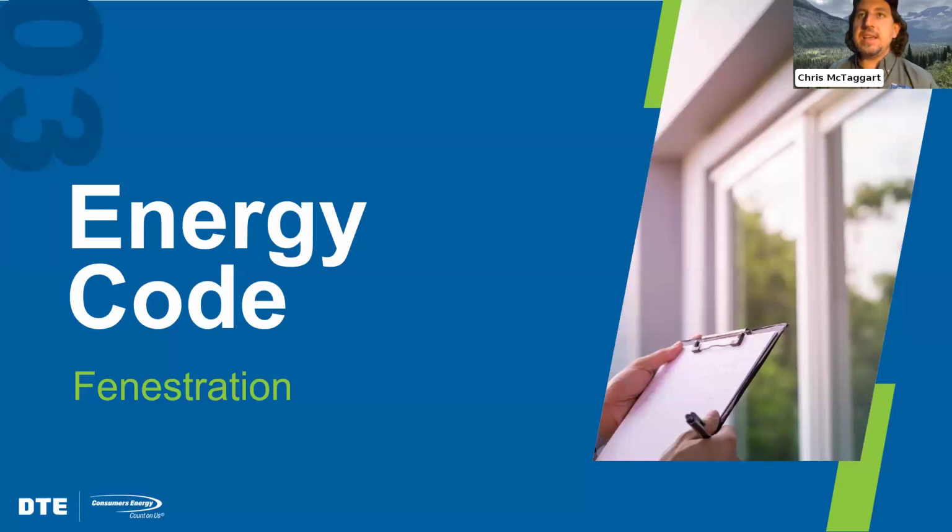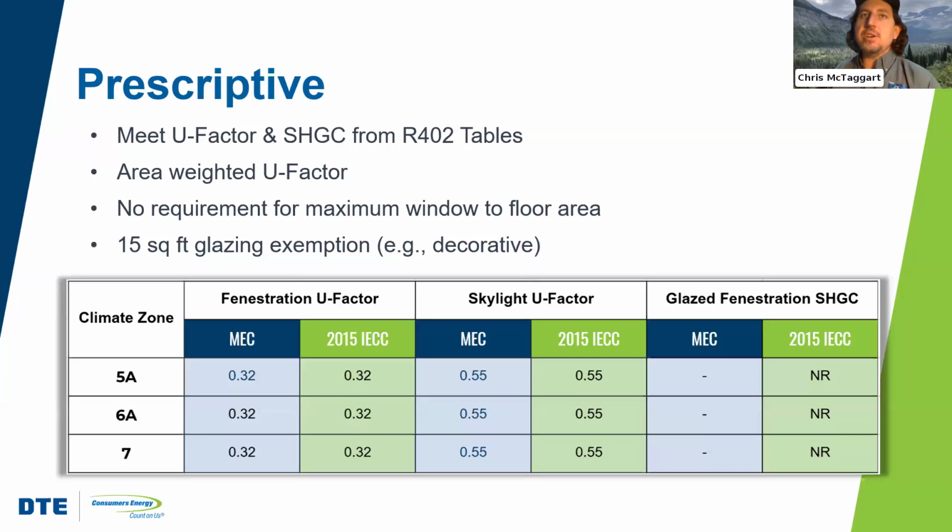Okay, jumping into windows in code. Michigan's energy code prescriptively requires a 0.32 U factor and has no requirements for solar heat gain coefficient. Why? Because we are in a cold climate and solar heat gain coefficient is not regulated. There's a small amount that can be exempt from this for a decorative value, and you can do area weighting of U factor. So, you could have better performance on one side of the house and worse performance on the other side, and that would still work out. You can also do a total UA value, and that will work as well for the total house. So you could potentially trade off worse windows for better values in other parts of the home.